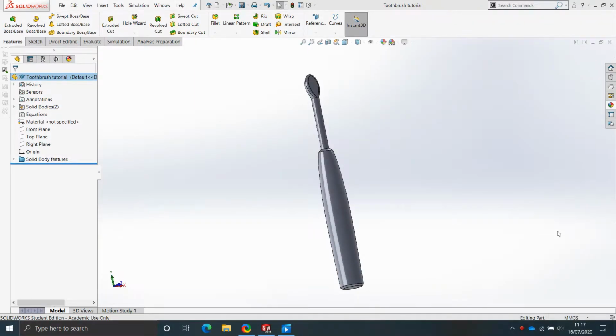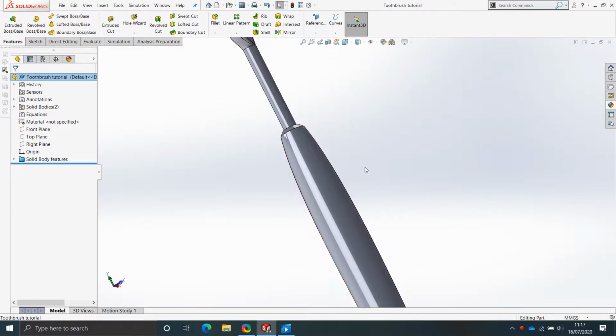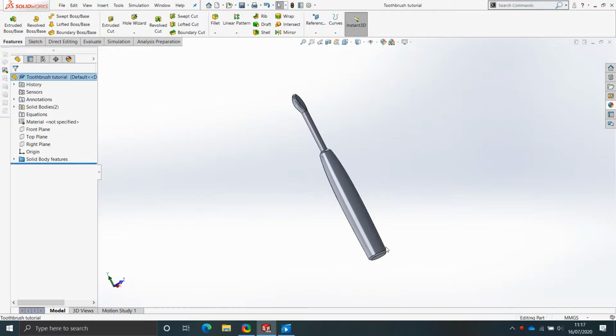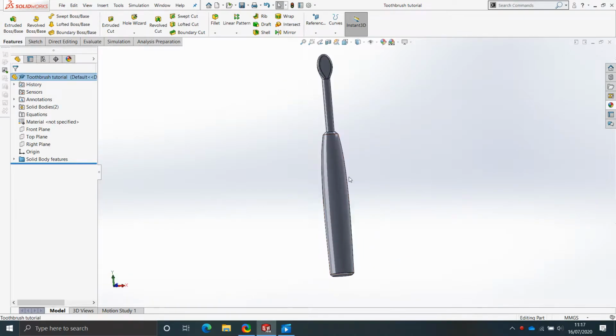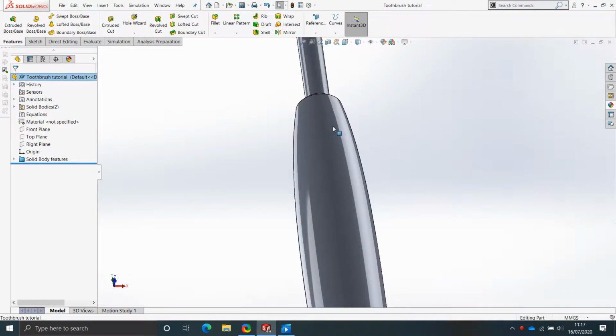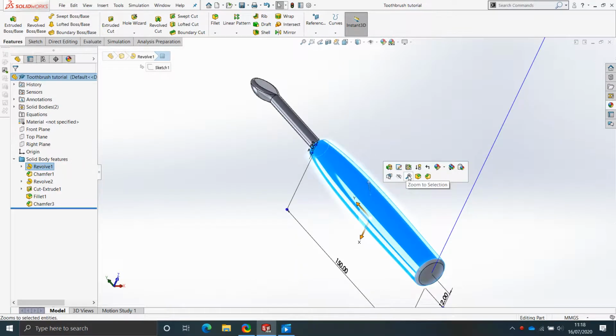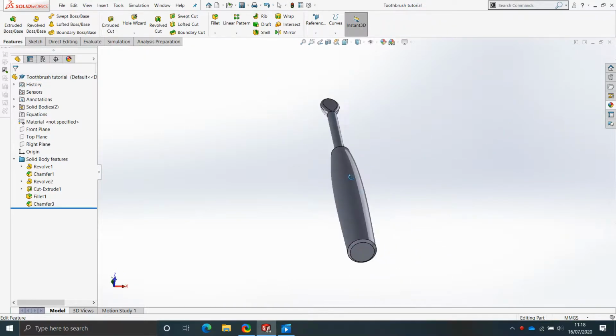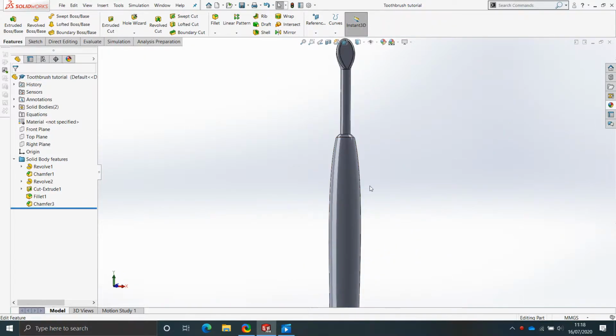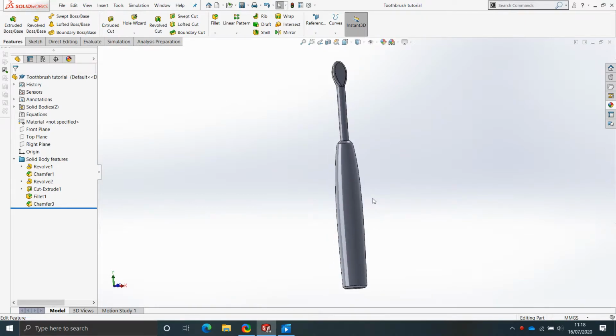In the first step, we're going to be looking at how to add a simple recess using only 3 surface commands. Here I have a model of an electric toothbrush, and so far all the features have been created using solid modeling. I now want to use surface modeling to create details on the front on this non-planar surface. It basically means I can't sketch on it and use solid modeling features with ease. I mean, I could use a wrap, but it won't give us as much control as surfacing does.